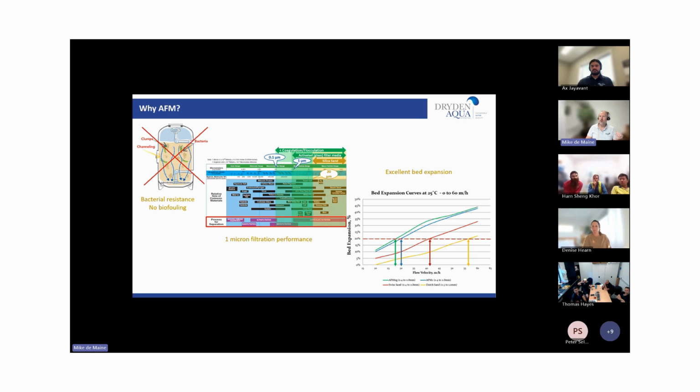The most important thing, and people always forget this when using media filtration, is not only how well your filter filters, but how well your media backwashes as well. Because unless you are backwashing your media correctly to release all of the dirt, your filter will always build up with debris over time.